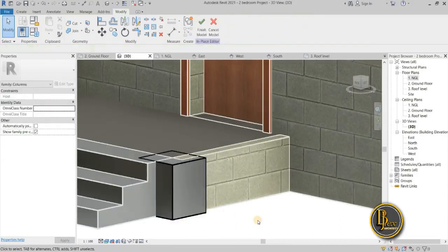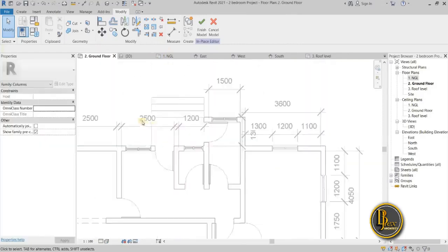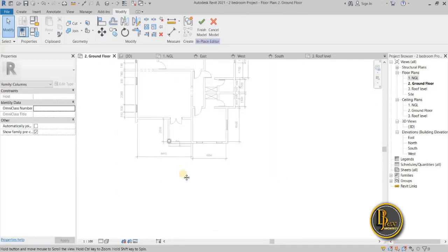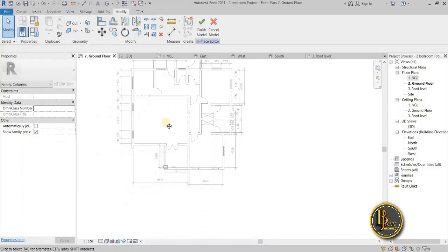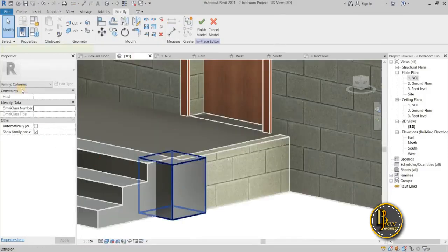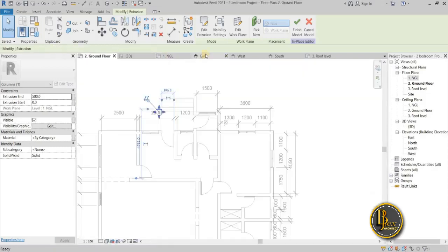Go to your ground floor view. Because we used 450, it is there, but it's not showing on your ground floor view. But we need the base of the column to be slightly above 450 so that it will show on that ground floor view. So let's change that particular column back to 500 instead of 450. Then if you would see it now on your ground floor view, once you click apply, you click OK, see the column showing on ground floor view.